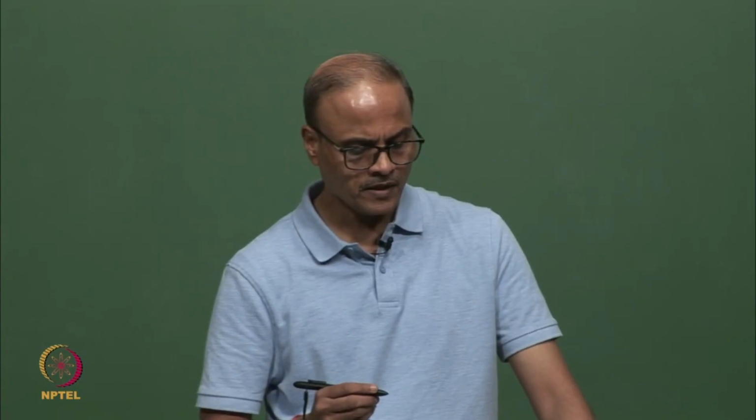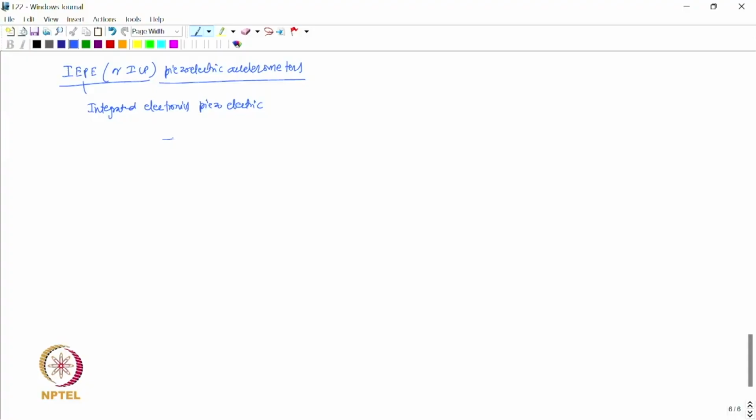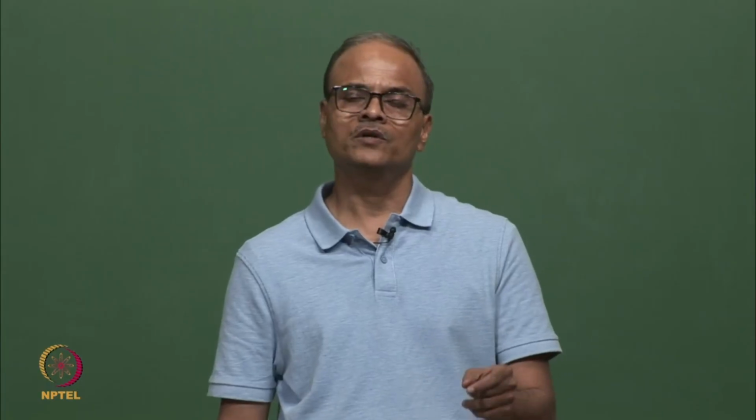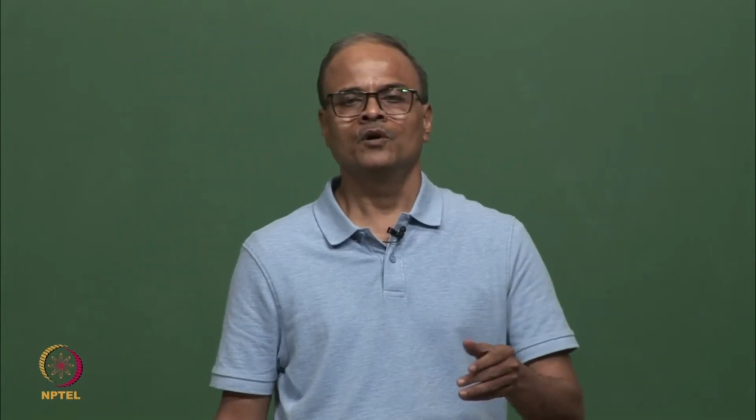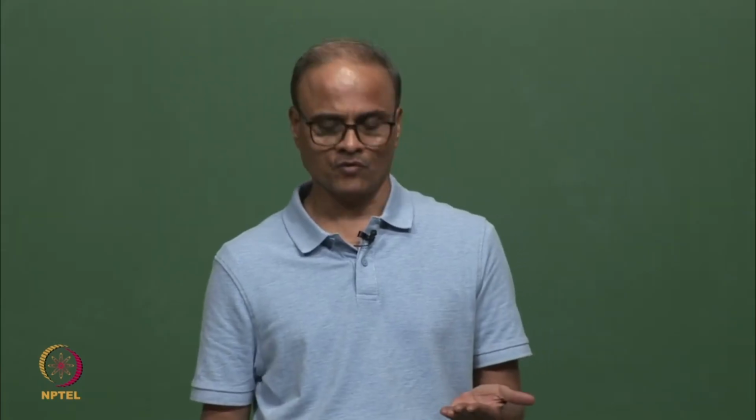These IEPE types of piezoelectric accelerometers have a built-in charge amplifier. A small IC which does the job of charge amplification is built into the transducer itself.